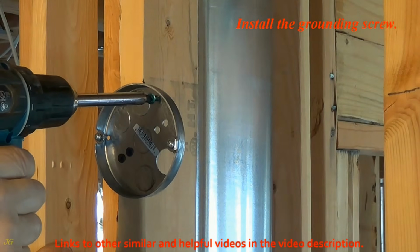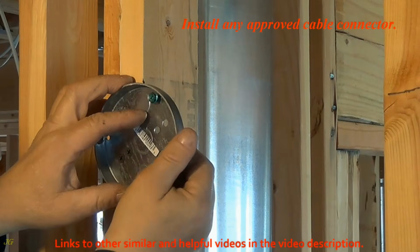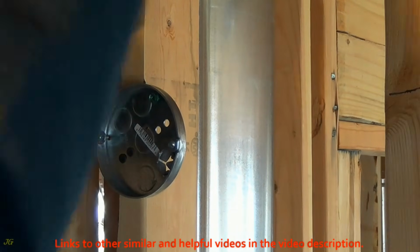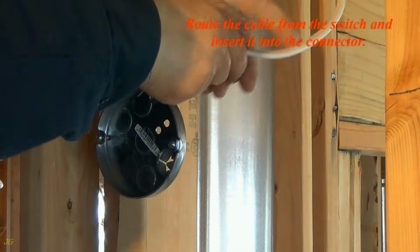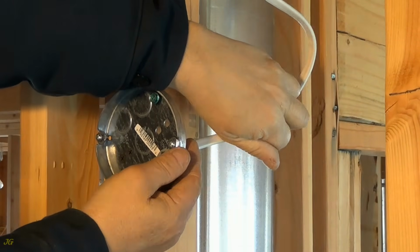Install the grounding screw. Install any approved cable connector. Route the cable from the switch and insert it into the connector.